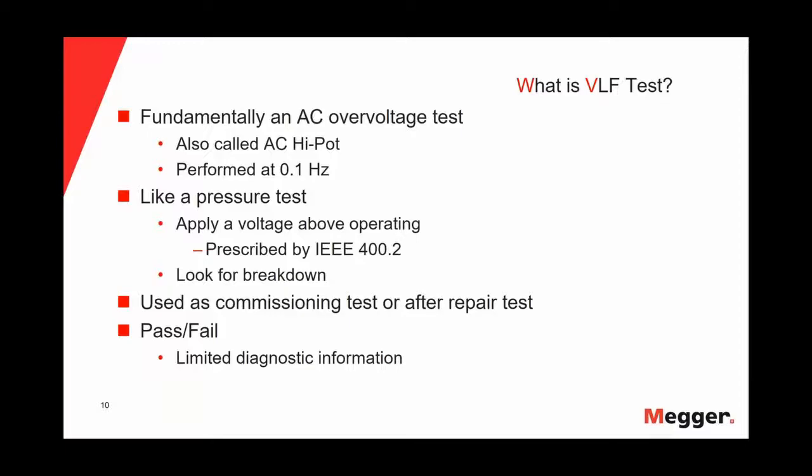What we want to do during a VLF test is convert into a fault the severe issues in the insulation or the accessories of my cable. We use the VLF test as a commissioning test or after-repair test, and it is a go, no go, or pass fail test. So we will have limited diagnostic information during the VLF test.